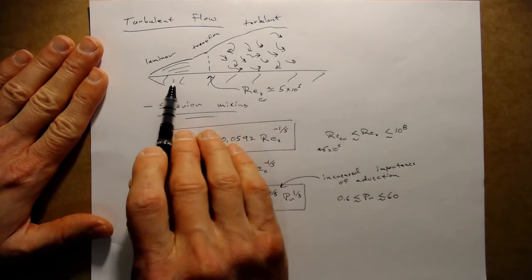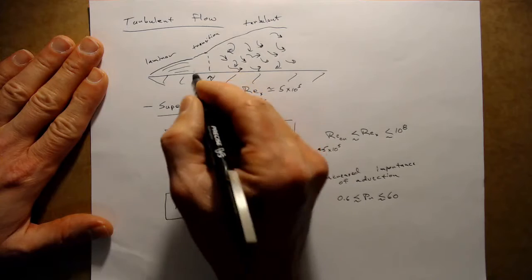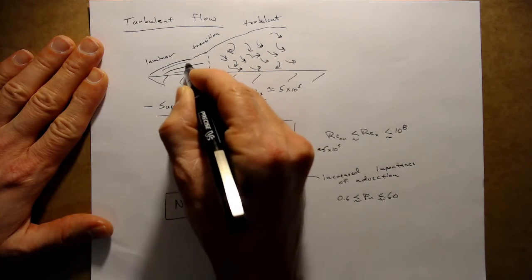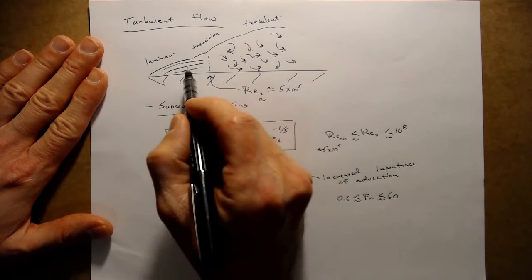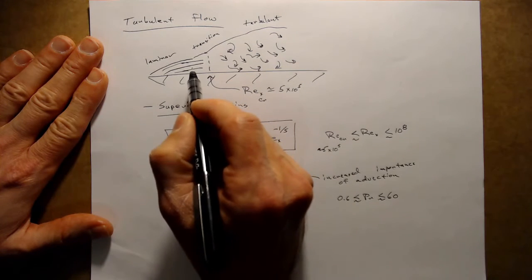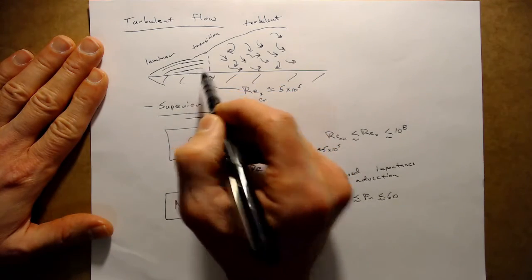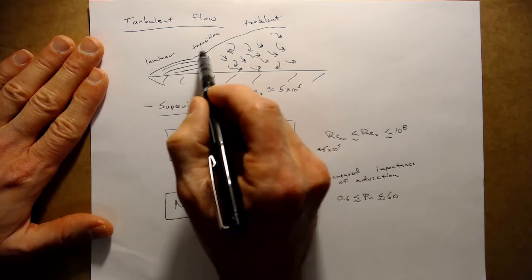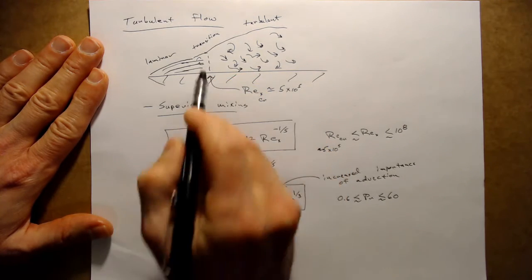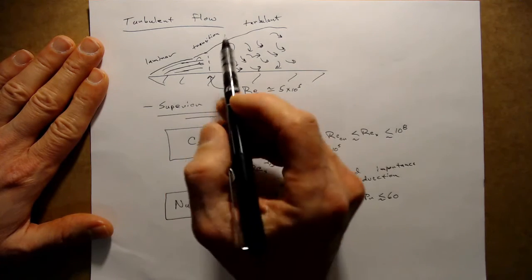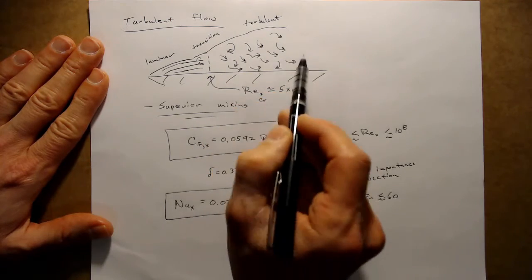Again, we remind ourselves we're looking at this transition from a smooth flow, where the streamlines, as we defined them before, that follow always tangent to the velocity of the fluid are smooth and continuous in the laminar regime. And then as we start to approach a critical Reynolds number, we start to see a transition where there is some instability in this flow. And then as we pass through this transition region, we achieve a turbulent flow.